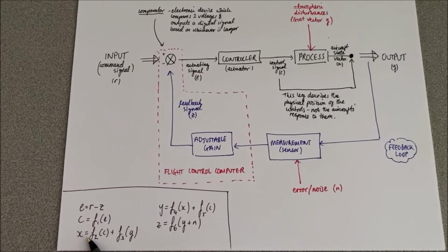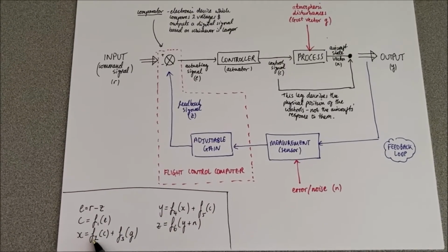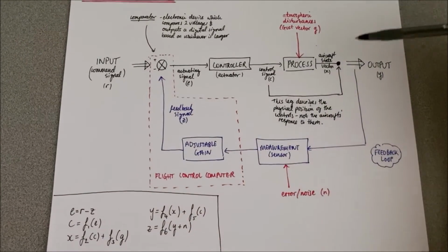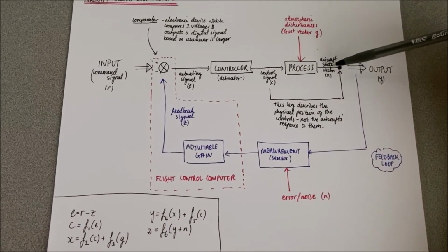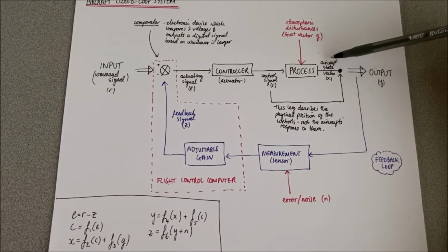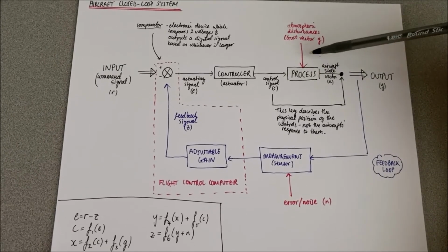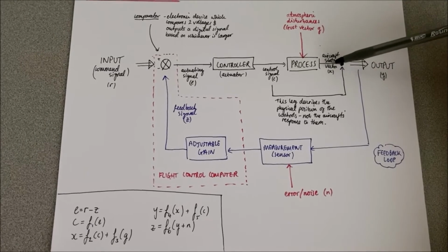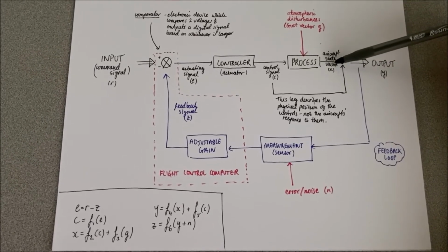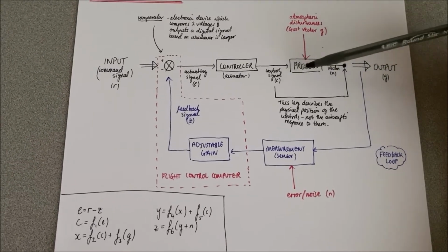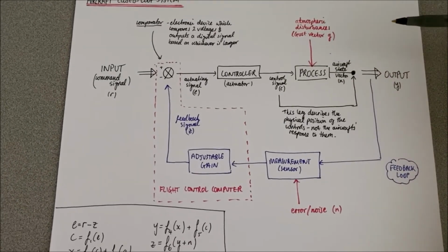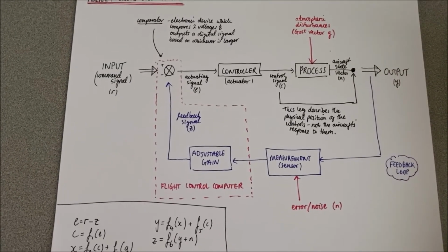So next we have the aircraft state vector X, which I've just added to this leg here. So that tells us the current condition of our aircraft, how the aircraft has responded to the control signal, and obviously that is a function of how the aircraft responded to that control signal plus any external atmospheric disturbance effects as well.